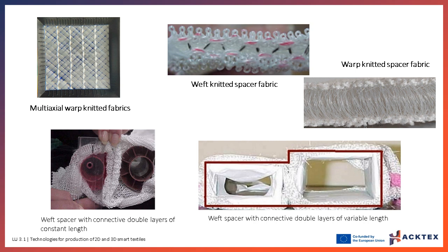For spacer fabrics, the 3-dimensional architecture is obtained by knitting separately 2 independent outer layers connected by yarns or knitted layers. The latter connection is specific to flat weft knitting and it involves stopping knitting on the 2 outer fabrics and knitting a layer that will connect both.